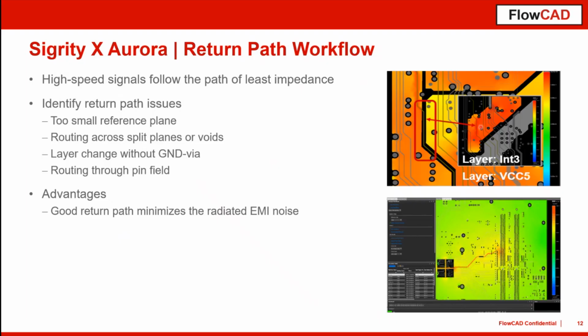And if you go to another layer, for example, to layer 2, where it's the ground plane, you also see that the return path also runs over this area. And as a conclusion, you can say, okay, hey, the return path goes somewhere unpredictable through my complete design, and that can cause a lot of EMI issues, noise, radiation, and so on. Therefore, it should be avoided in this case.